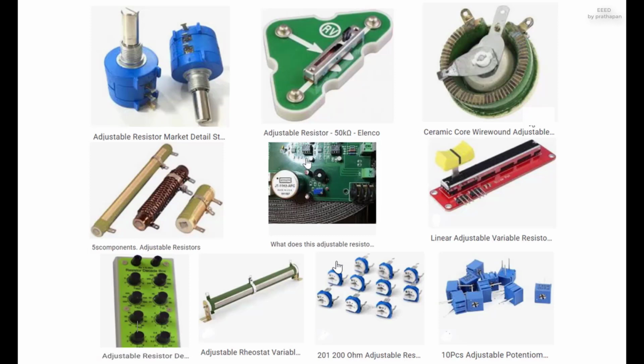These have wire wound resistance elements typically wound on a helical mandrel, with the wiper moving on a helical track as the control is turned, making continuous contact with the wire. Some include a conductive plastic resistance coating over the wire to improve resolution. These typically offer 10 turns of their shafts to cover their full range.